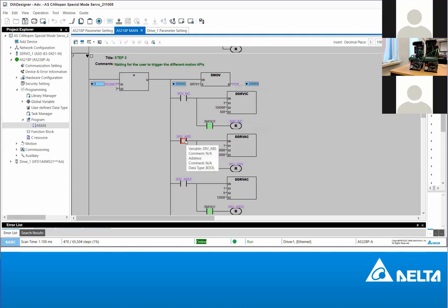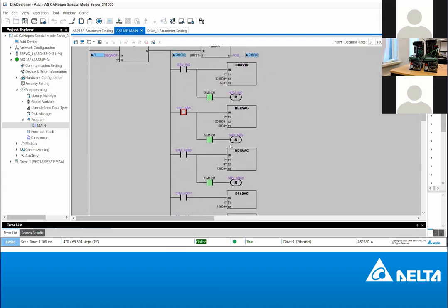If I trigger this command again, you see nothing happens, because it's already in the absolute position. It will never move because it has gotten to that position that I want. So that's different. Incrementer will always increment to a new position that you have specified. But when it is absolute, this is the position that is absolute. It will not move anymore.